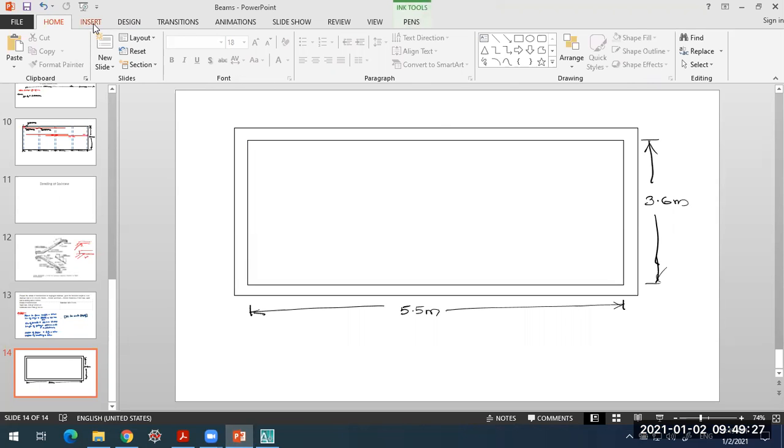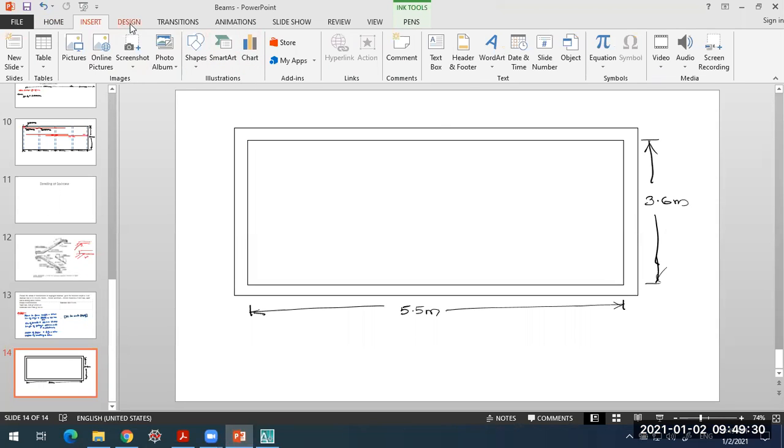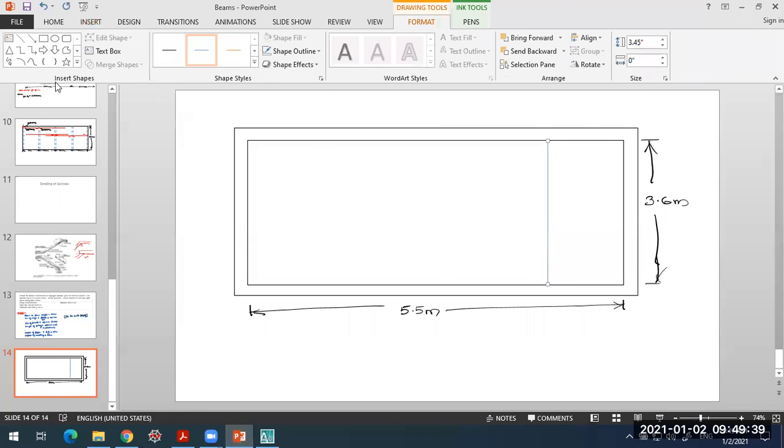Anyhow, we'll draw it in the AutoCAD. So first is the landing. Okay, so this will be 1.8 meter. And the staircase, 2 flights. So they will be 1.8, 1.8 each. So these are the 2 flights, and what we have here will be the space available at the entrance. Okay, so this is the staircase hall.